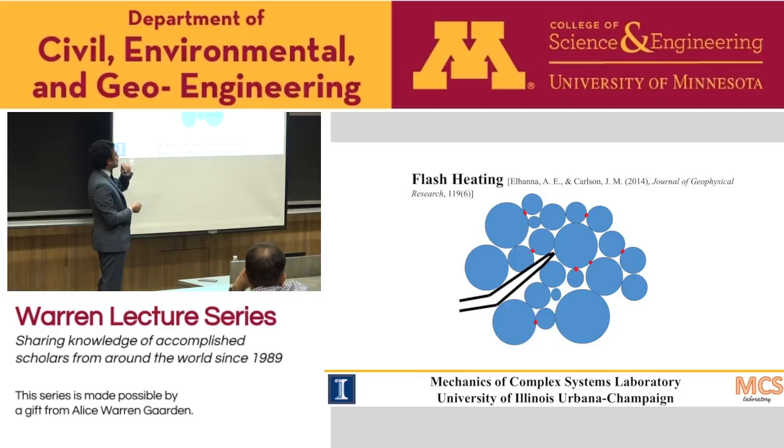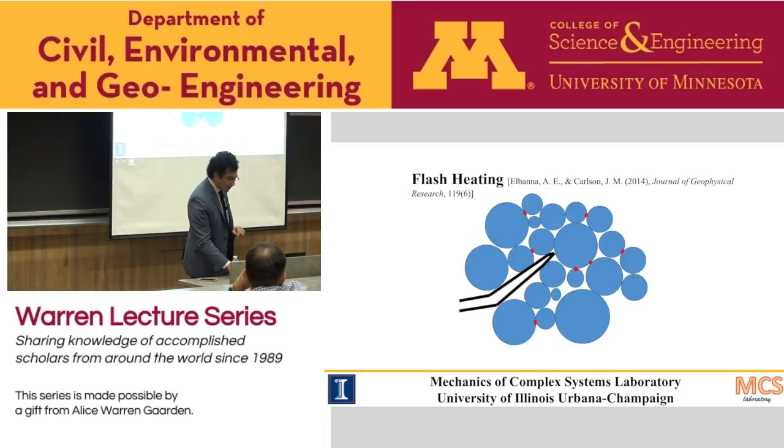You can solve a local diffusion, heat diffusion equation to track the temperature of the contact. And by tracking the temperature of the contact, you can feed back into the contact strength, which feeds back into the viscoplastic formulation. So that's one example. The other example is grain breakage.